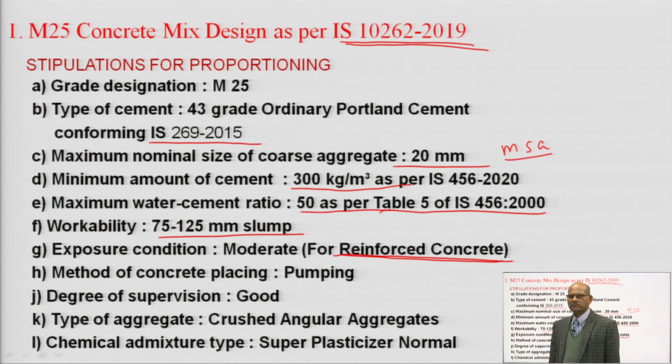So, degree of supervision is also important. If the degree of supervision is not good, then we have to increase the mean target strength. So, this part will also come into the picture. That will be given here, and then we have the type of aggregate. We have different types of aggregate. Here we are using crushed angular aggregates.